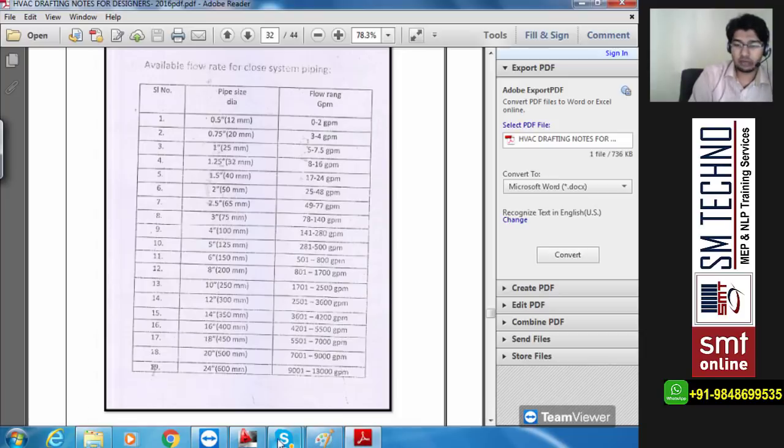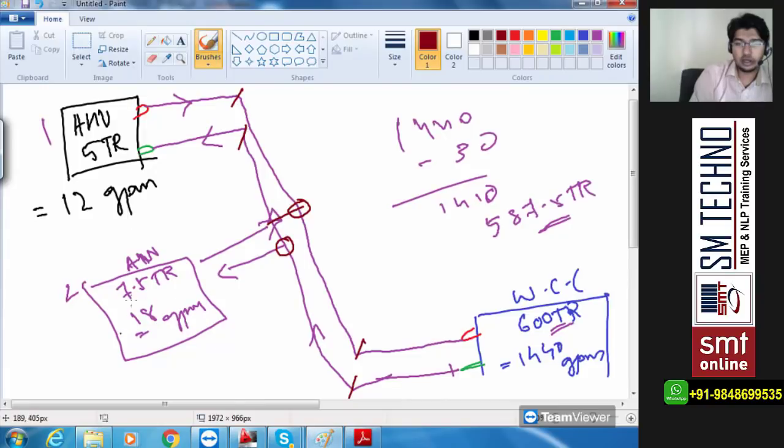Yes. So if I'm going to come back to my drawing, we are going to consider these 40 mm pipes are the ones through which the water is moving into the AHU. Now what will happen if I'm going to keep 200 mm of pipe here also, same as the riser? Can I only get 18 GPM? No, there is a chance of more water flowing. Why? Because the orifice of the pipe is much larger. All right. So I cannot do that.